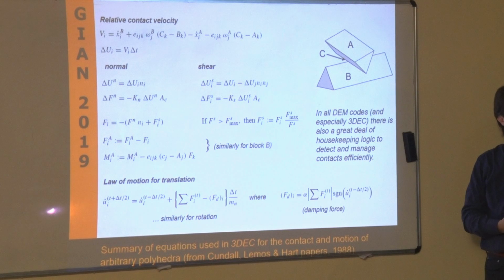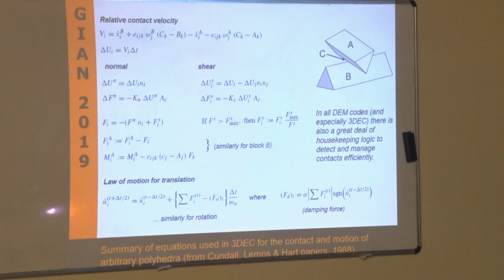So when you're looking at discrete elements, you have a block, and you need to understand when this block is getting closer and closer to another one. When it's ready, you interact with the other one, and if it's going to interact, what are the forces that they are going to exchange with each other? So it's action and reaction forces.